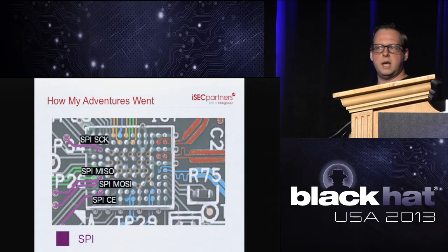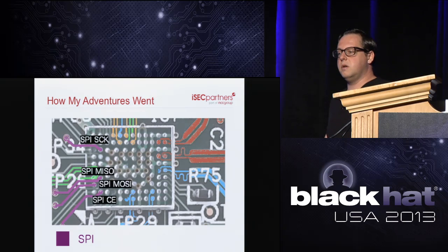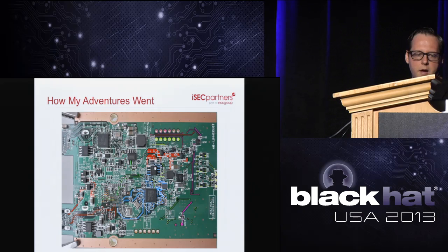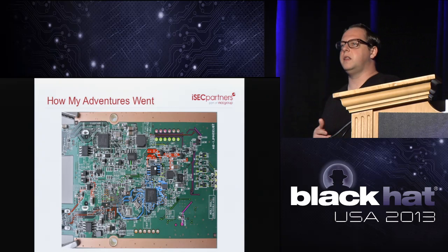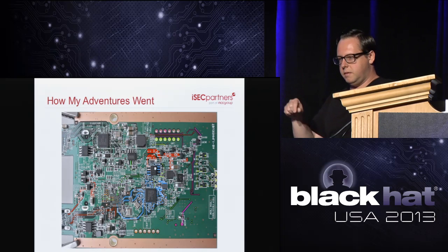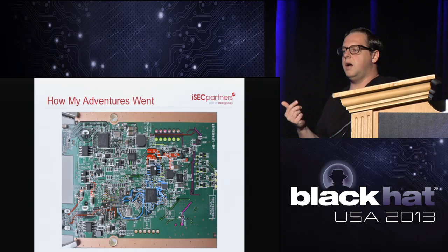So not only do we know we have some code we can look at, we also know that we have 4 more pins that we can add to our list of pins for Thunderbolt. And so we kind of do this process. We start developing this map of how all these things are working together. We use color-coded lines to trace out things. I chose blue for PCI Express, red for voltage.